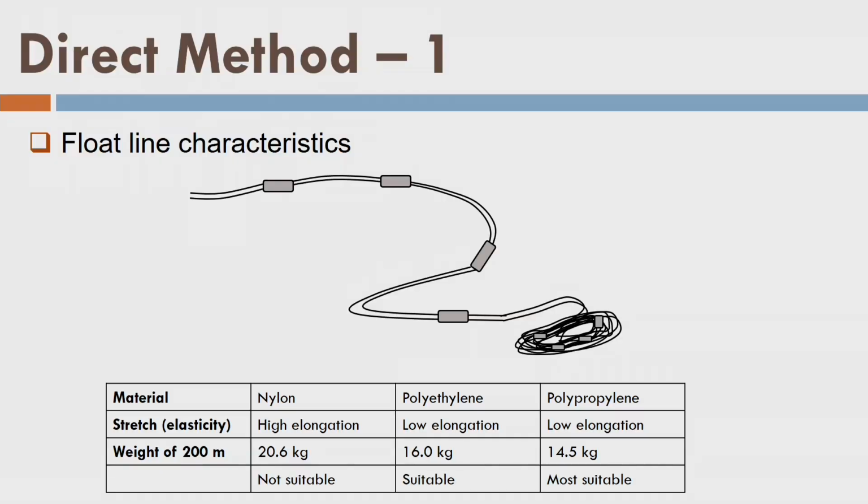Now, what do we do here? Basically, we stretch a float line. Let me tell you about the float line. We take the float line, and one end of the float line is tied at the reference mark. Remember, we have marked 3 references on the screen. So, at one of the reference marks where I am putting this optical square, there itself we make a peg, or make some kind of knot,